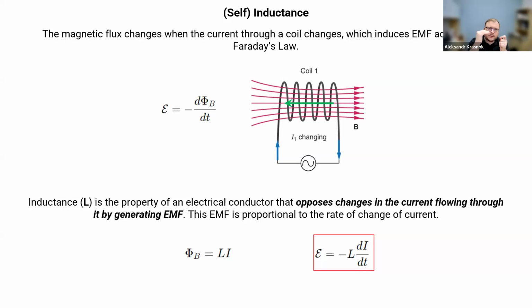And there is a fundamental frequency above which you cannot use your processor because of the self-inductance of every single conductor. So that's why it's so important to know about this and be able to calculate the inductance of any wire.